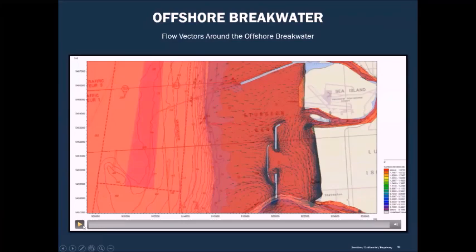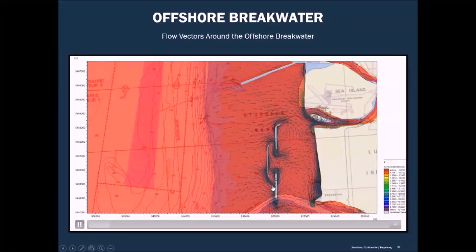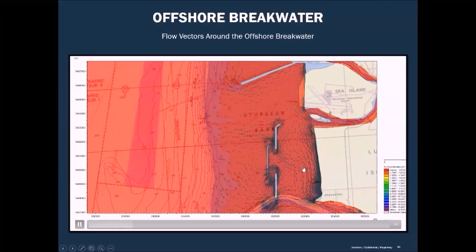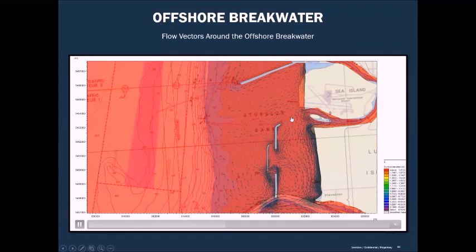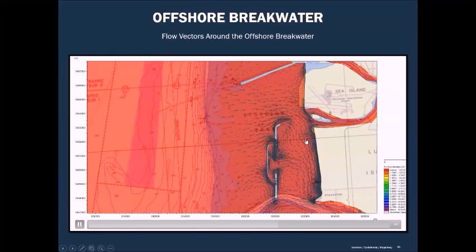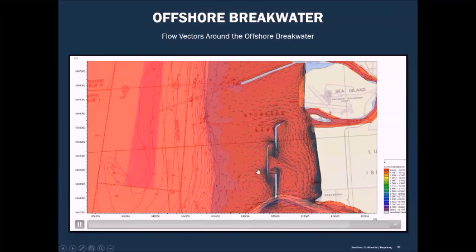So we can look at the flow pattern inside this zone. When you place this breakwater, you can see the velocity pattern has been changed. The wave is not coming directly, the wave is coming here, and the flow pattern has been changed. And then the sediment transport also changed in this area. There should be identified, or there should be considered in this model what will be the best location and what will be the appropriate size for this breakwater. It will be like a trial and error.